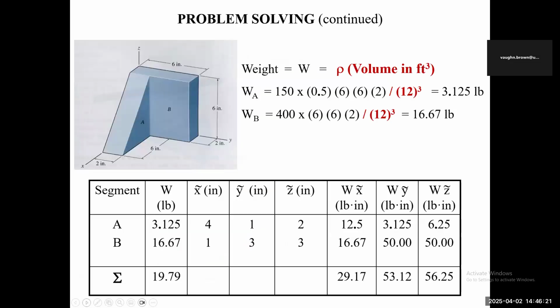And then I'm going to ask you some questions here. So they want you to calculate the weight. You know that the density times volume will give you the weight. So how did you find the volume here? The volume would have been the area of the triangle here, which is half base times height. The base is 6. What is the height? 6. So it's half base times height, which is right here. And you're able to find the area of the face here, the rectangle face.